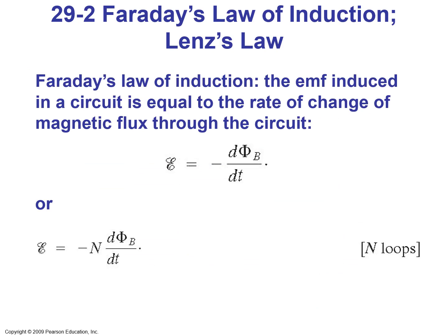Faraday's law of induction says the EMF induced in a circuit is equal to the rate of change of magnetic flux through the circuit. So EMF equals minus d phi over dt, the derivative of the magnetic flux with respect to time, and it has a negative sign, so it opposes the changes in the flux. Or for N loops, EMF is equal to minus N times the rate of change of flux over time.